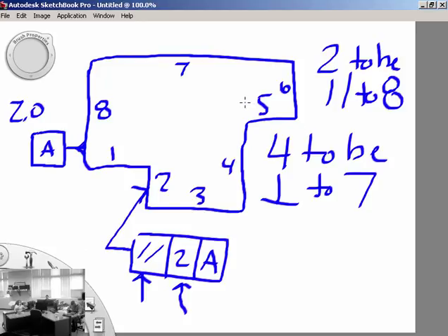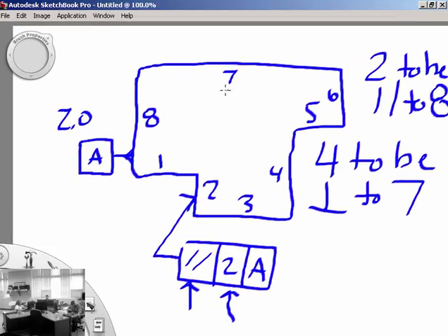Alright, now I'm going to use this as an opportunity to show you something. On a set of plans, they won't always be nice and neat and show you a datum here. By the way, I can't name this A again, can I? Now I have to name it the next letter down, or whatever letter you choose. But they may not always be nice and neat and give you this perfect understanding of where this datum is. They may do stuff like this. They may have a dimension out here about something, and just ignore that my 2 happens to be written there. And they will attach the datum to the dimension.